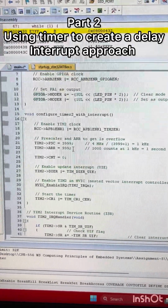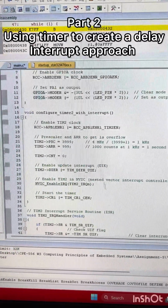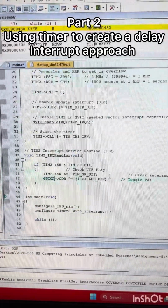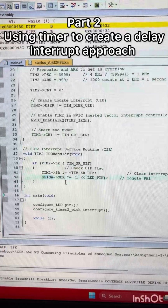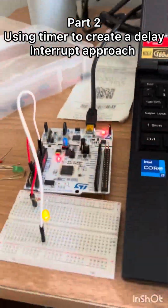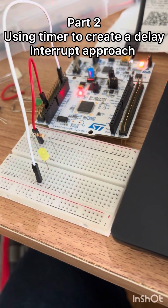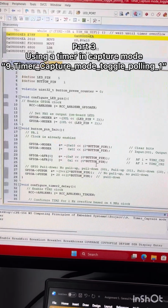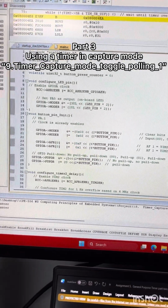Every time the counter reaches the limit, the update interrupt flag gets triggered and the LED gets toggled. Here is the practical demonstration where we have used the same setup but a different method to toggle the LED. This is part 3, using a timer in capture mode.